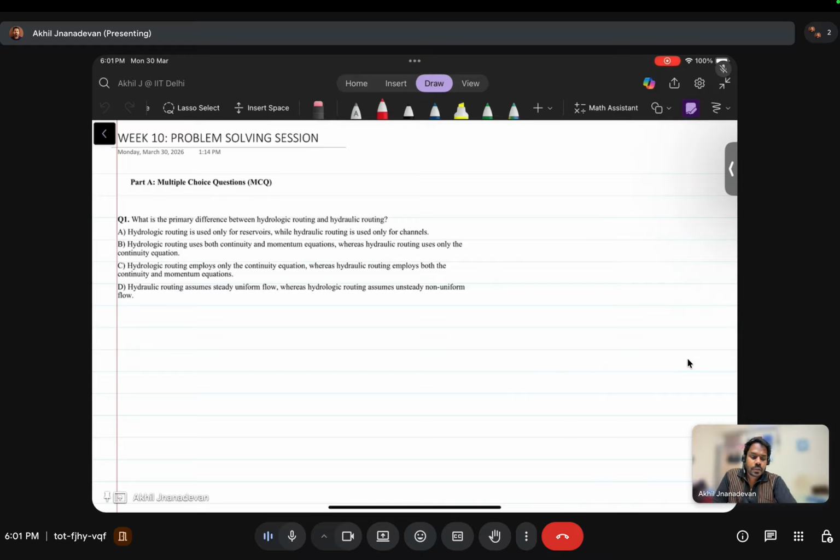Hydrographs arise when precipitation occurs in a catchment or watershed: the water that falls on the watershed fills the different types of storages, then the overland flow starts, and this overland flow, or sheet flow, gets distributed and forms a network of channels called the stream flows.